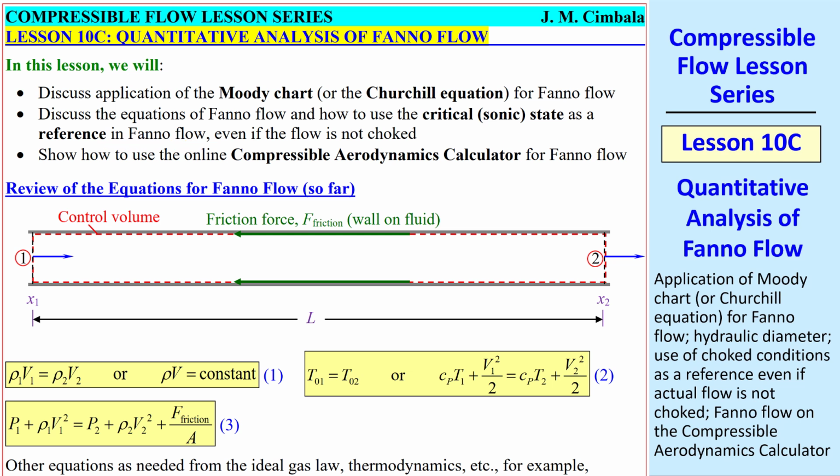And as we've seen previously in other kinds of flows, we can use this reference value at the sonic state even if the flow is not choked. In other words, even if this state never exists in the flow. And finally, I'll show you how to use the CAC for Fanno-flow.